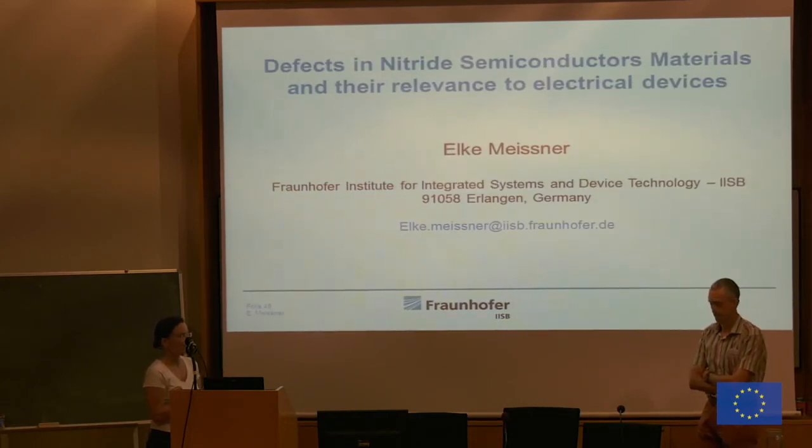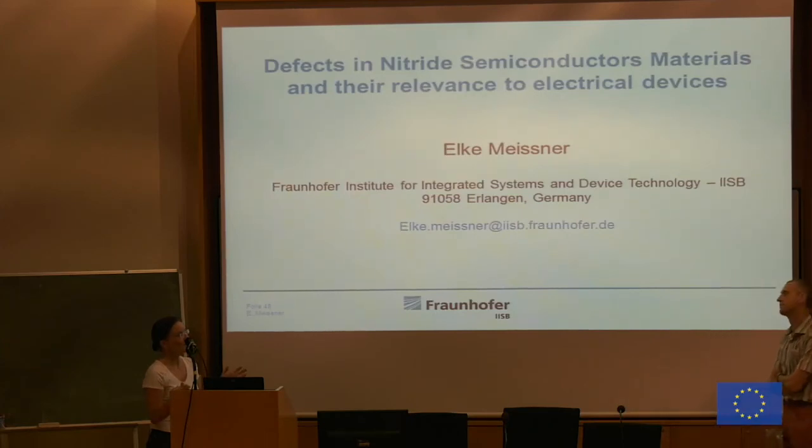On the other hand, it's more difficult to scale it up to larger areas. So if you want to have a 150 millimeter or 100 millimeter crystal. And this was also the case for the silicon carbide. The most challenging thing in the silicon carbide growth is now the scale up to 150 millimeters. This is kind of easier in an HVPE growth process with the gallium nitride.